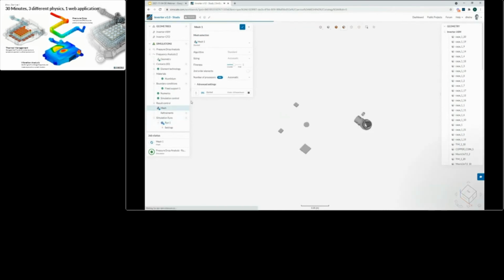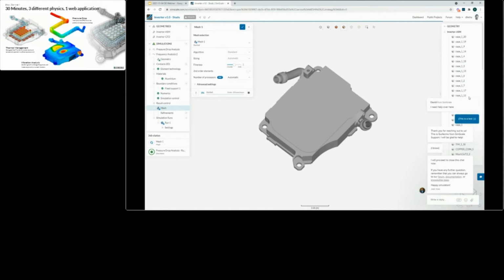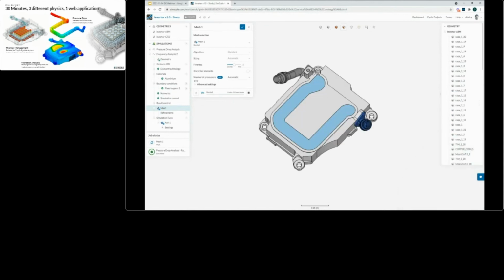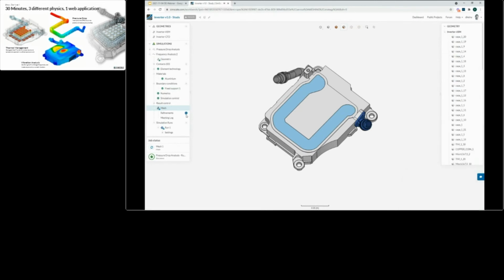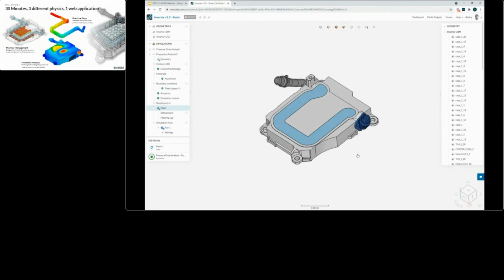I could now go into a lot of detail in here. Drive local sizing. I could go into more advanced parameters, specifically when there are certain regions I'm interested in, or I'm doing a mesh sensitivity study, or these types of things. But if I don't do any of that, the application itself uses heuristics, machine learning models, in order to come up with good default setups for this.